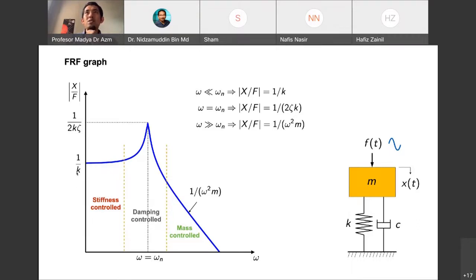So then the level of vibration is controlled by the stiffness. So 1 over k means if you want to reduce the level, we have to increase k. So this is what the graph is telling us. If you want to reduce this level, you have to increase k. It means you have to make the mounting stiff, or the flexibility, the motions of the machine, to be restrained.